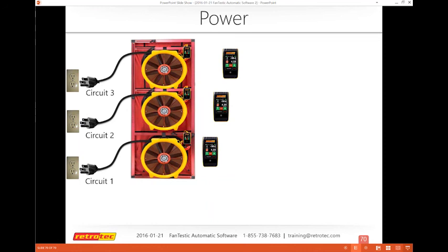Essentially, when the operator is moving around, let's say, for example, you're doing a combustion blind zone test, and you're walking around the house, opening and closing doors and so on, then you can do this by having your cell phone in your hand. You can be watching the pressure and so on, so you don't want to be dragging tubes all over the place. But if you're dealing with a static situation where the components, the gauges, etc., aren't moving, you might as well hardwire them together, even if that gauge is, say, on the third floor. You want to hardwire them together because you're not moving around.